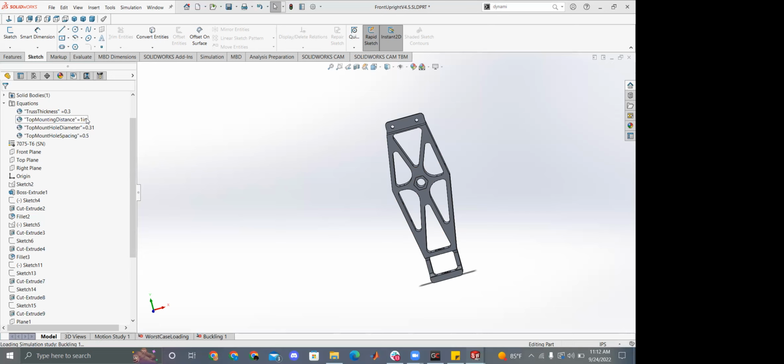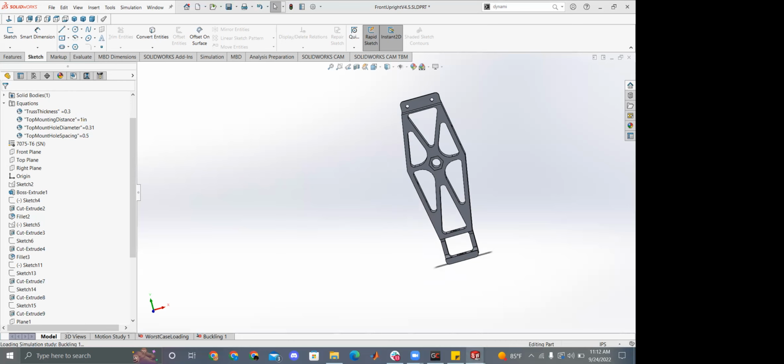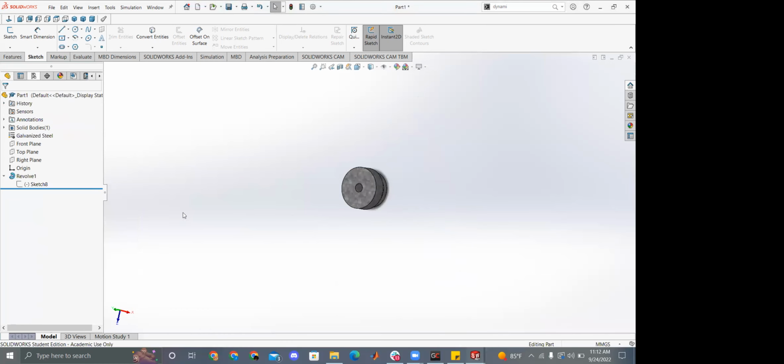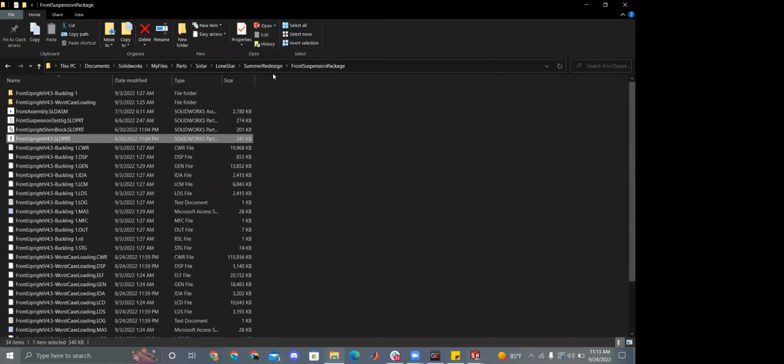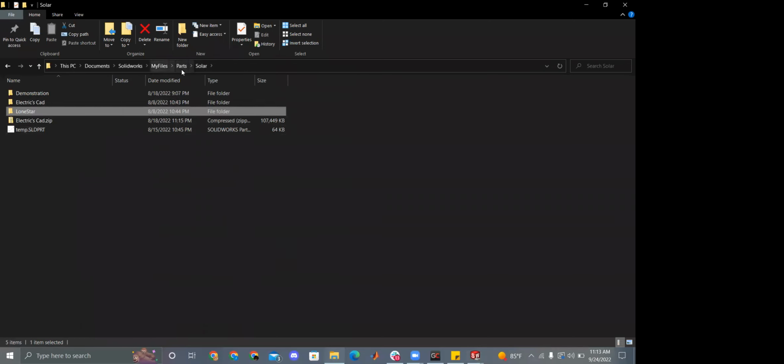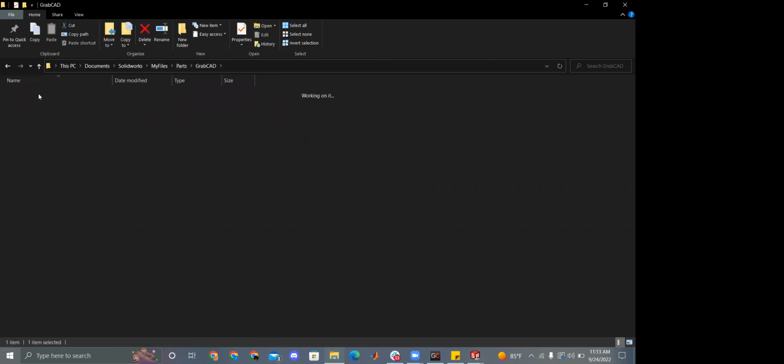Well, actually, I was going to mention that you can make one a driven dimension. So it doesn't affect the sketch, it just basically shows you that distance, right? I think having driven dimensions is nice, because if you want to know the distance between something, you don't have to measure it, it just shows it in the steps.